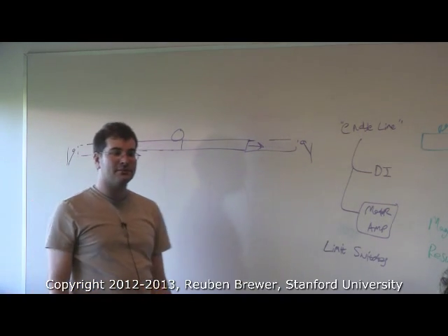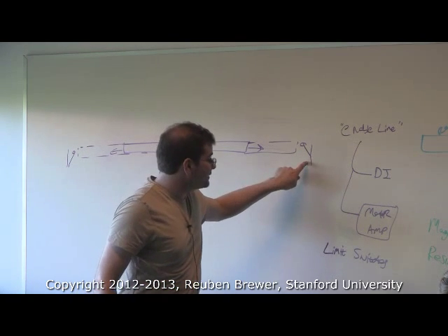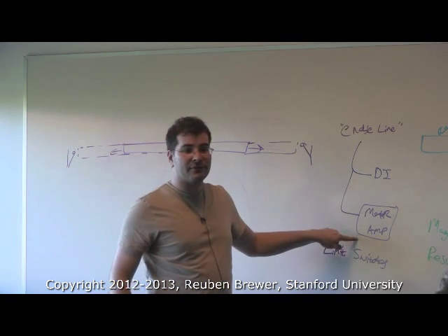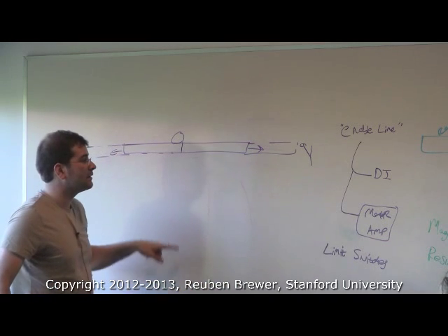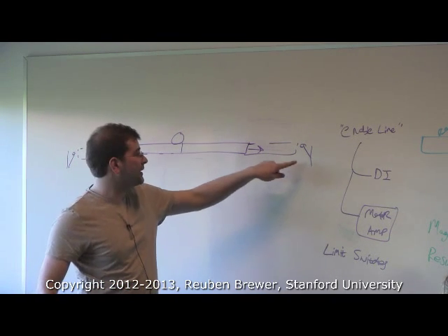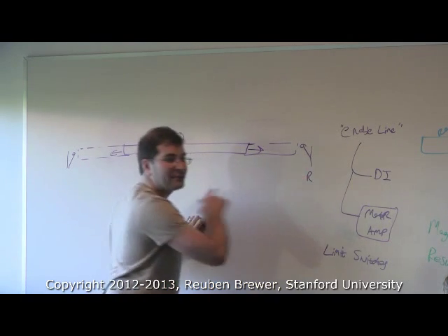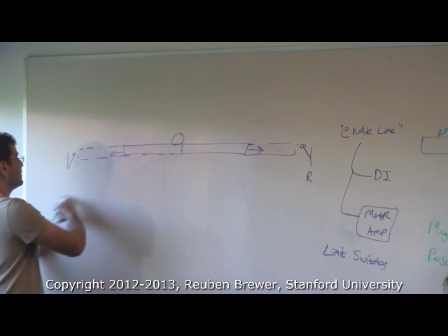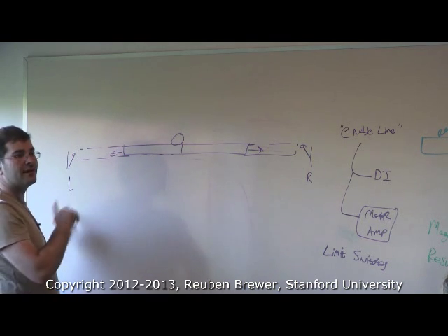On really nice amps such as Copley, you feed this electrical signal into your motor amp. And what happens is it stops moving in that direction only. So if you hit the right limit switch, it can't move right, but it can still move left. If it hits the left limit switch, it can't move left, but it can still move right.